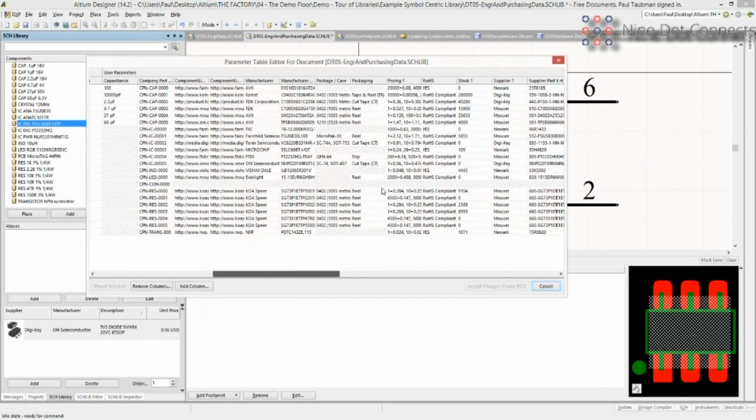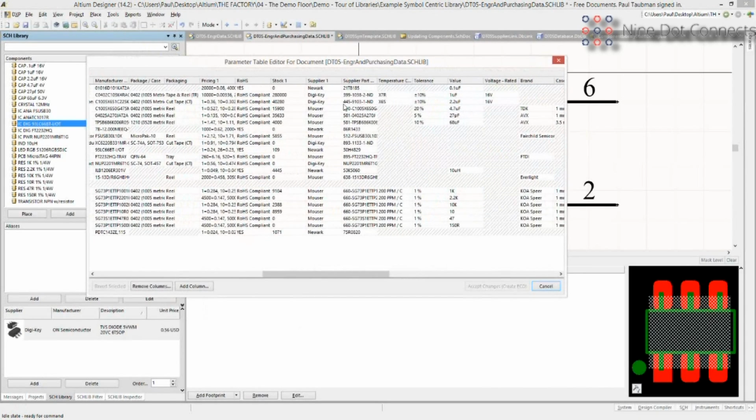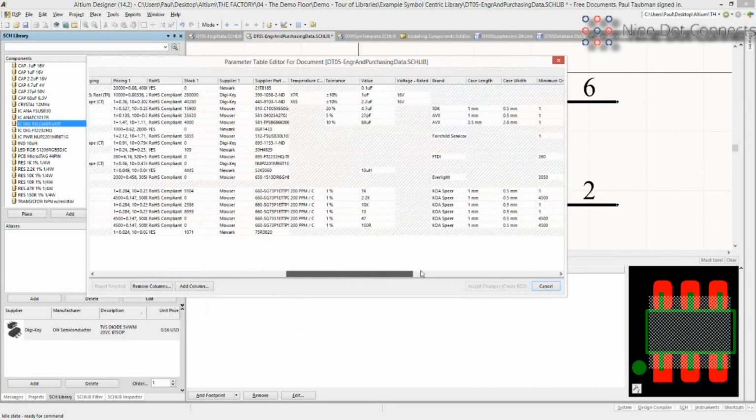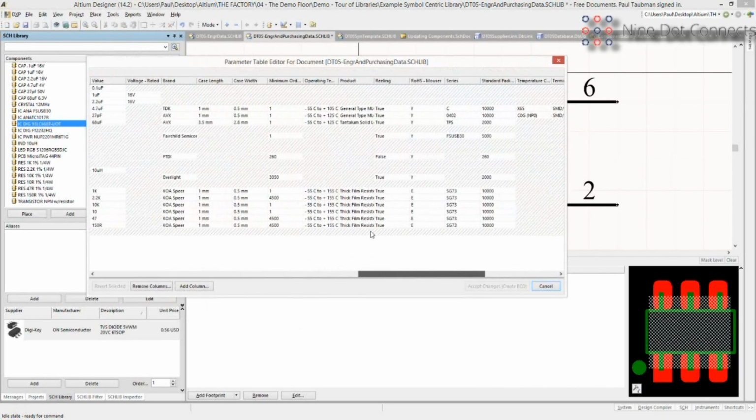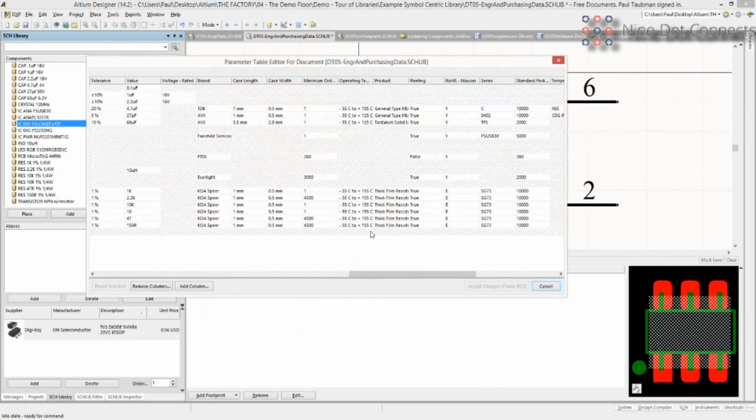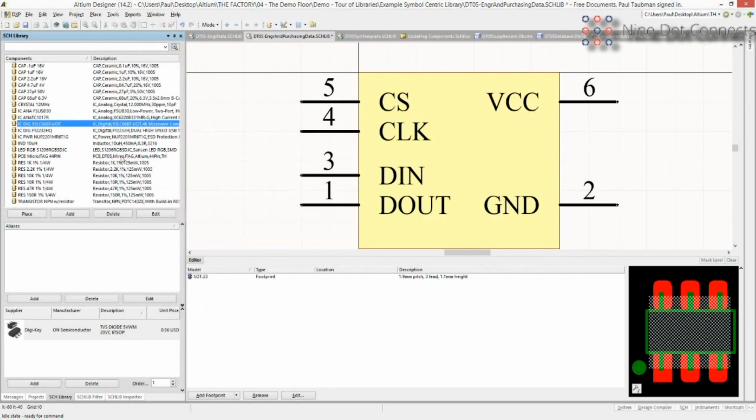Now, not every single one of these columns is going to be filled up, right? Or it may have different data. So here's the temperature coefficient. If you're dealing with capacitors, they have their own nomenclature for that. If you're doing resistors, they use parts per million degrees centigrade. All right, or there may not be a tolerance associated with it because these might be IC parts as opposed to capacitors or resistors. Some of the stuff you may want to keep, others you may not want to fill in, or you may not find it pertinent. It's up to you. But the key thing that I'd recommend when you're doing these type of libraries, and this is true across all libraries, is you want to keep the static data that's going to be true tomorrow, true next week, and true 10 years from now. Okay? So that's the key thing about this. And this is the type of libraries I mentioned earlier. People have used this one for years.